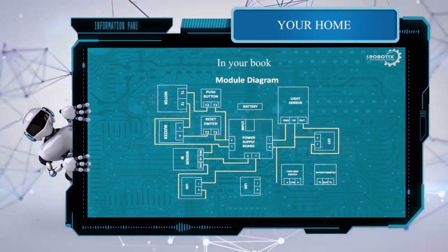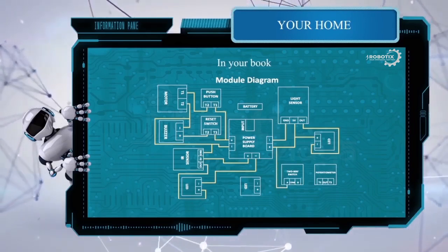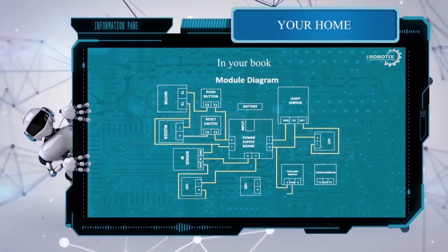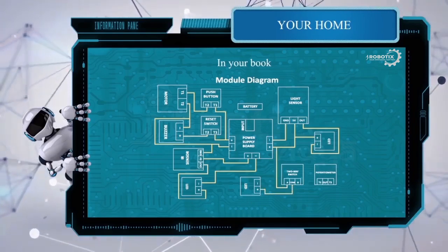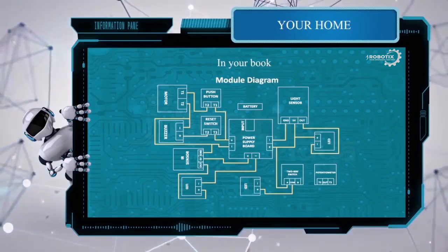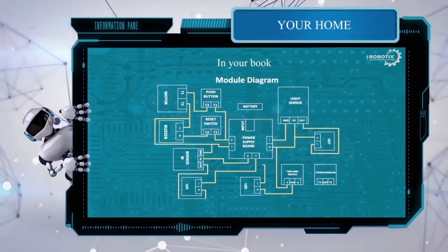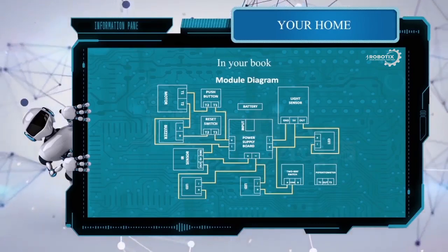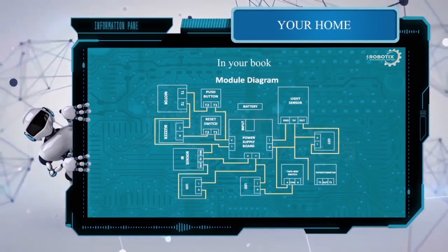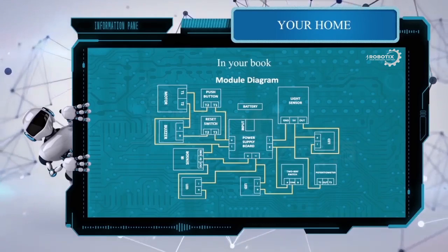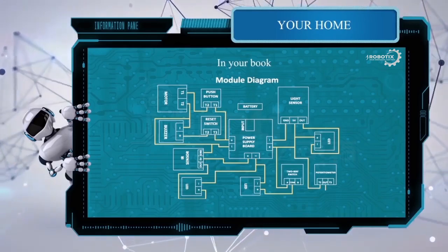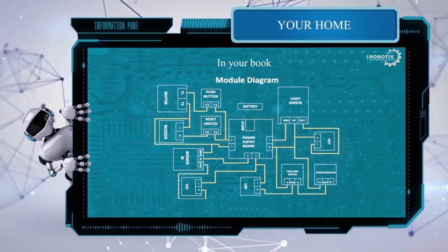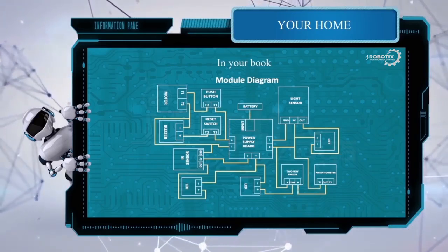So connect the positive of your power supply board to the terminal A of your two-way switch and the common of two-way switch to the positive of your LED and the negative of your LED to power supply board's negative. Next, connect the positive of your power supply board to T1 of your potentiometer and the output of your potentiometer to terminal B of your two-way switch. That's it. Your model diagram is done.